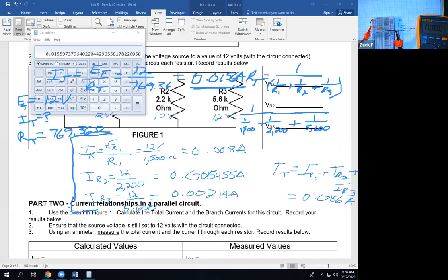a breaker? Yep. What about the old-fashioned fuses? Remember when I showed you those on that old panel? You start blowing a fuse? You put a penny in there. Yeah, so you put a penny in or a bigger fuse, right? No. The fuse is doing its job. It's telling you there's too much current for this wire. The wire is going to burn up if you keep adding things to the circuit. The fuse is doing its job. So you put a bigger fuse in there, you put a bigger breaker in your panel to handle more load without upsizing the wire that's feeding that circuit, you're going to have a house fire, right? So that's why it's important to know what current does in a circuit in parallel.